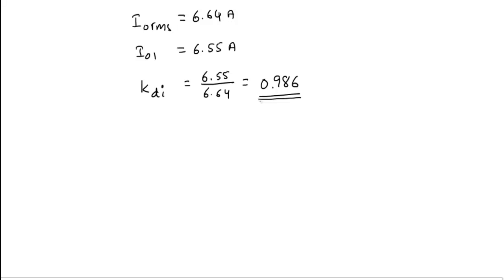So that means it's very close to 100%. That means harmonic content is reduced. That is because of the inductance. If inductance is not there, this will be 0.9. So that is the advantage. If you have the inductance, it will filter out the harmonics. Now you can see the other thing, percentage THD. This indicates how much harmonic content is there in the load current. Remember, in the case of single phase inverters, voltage will not depend on any current waveform or any load. That's why it is always a square wave.